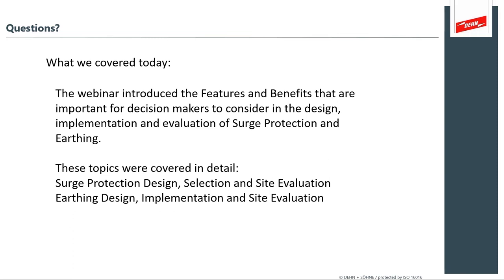So the risk assessment will tell you the measures you need to put in place, and that helps you pick the surge protection device and the energy it needs to withstand. This is one of the advantages of IEC methods: it allows you to select higher and higher levels of risk control for things like a hospital with explosive environments, oxygen atmospheres, and people that are very difficult to evacuate, where you have a high risk of fire and a high risk of life threat.